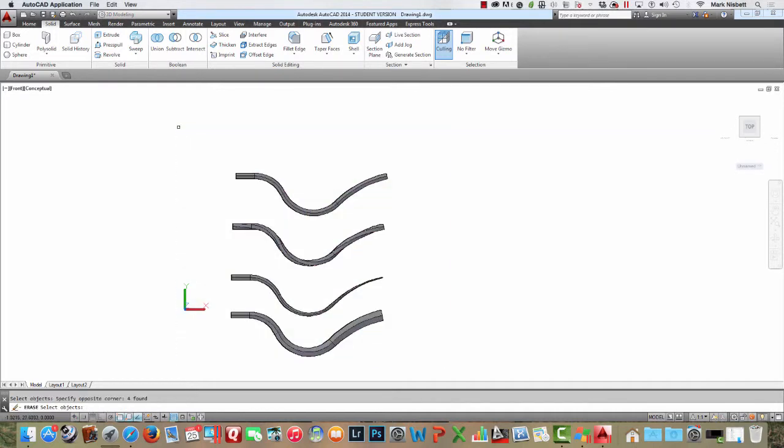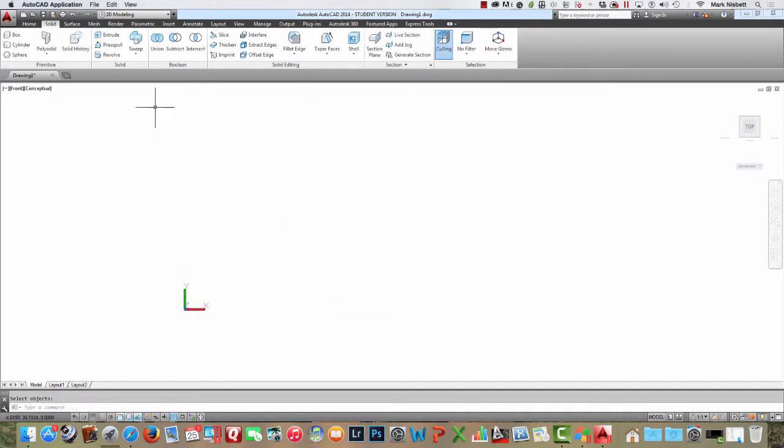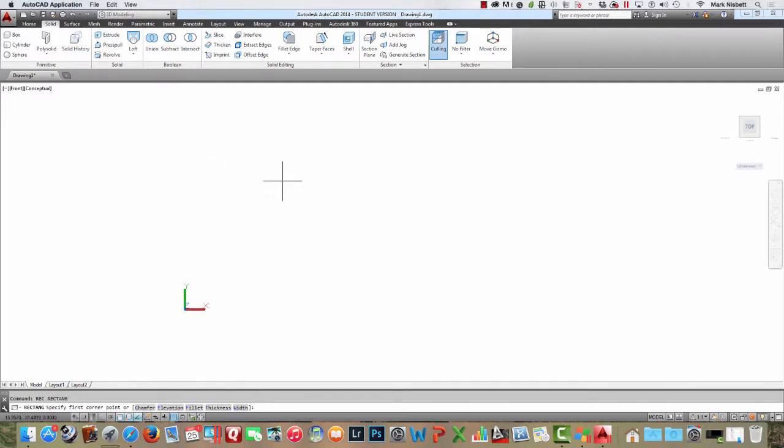And then I just introduced you into the lofting command, which is underneath sweep here. And the loft command basically will take two shapes and put a solid model onto them. So for instance, if we had, say, a rectangle like this, and we had a circle like this, okay, they would have to be separated in 3D space.